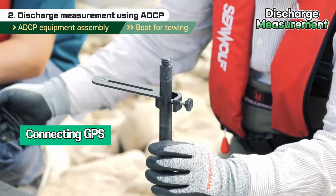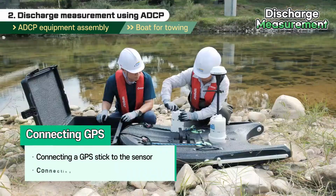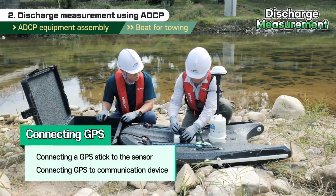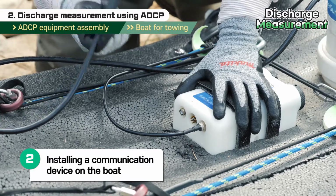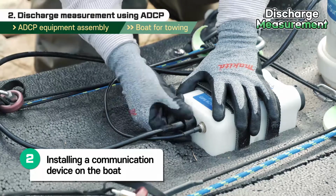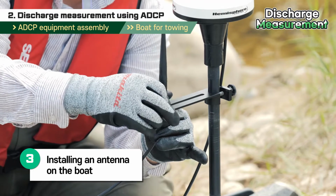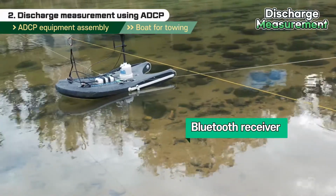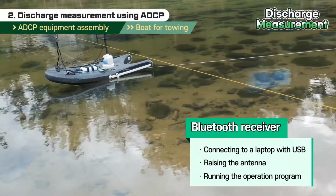For the GPS, the connecting stick is connected to the sensor first. Using the cable, we connect the GPS with the communication device. Next, the on-site worker installs the communication device in the middle part of the boat. The device is connected to the ADCP with a cable. Then the antenna is installed on the boat for transmitting measurement data. The receiver is connected to the laptop using a USB connector, and then we raise the antenna and run the operation program.